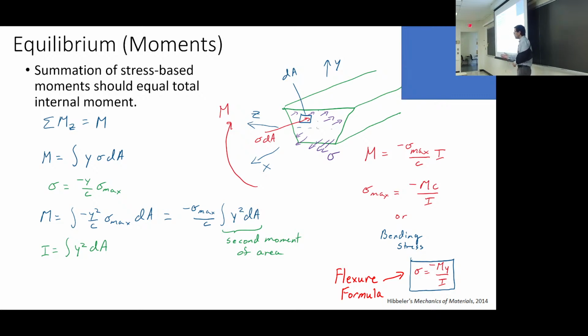And it shapes this idea that you saw in that slide of the truck moving across. That thing was bending moment, right? And you saw that there was a spike in the middle for the bending moment. That means that's where the stress is going to be the highest.